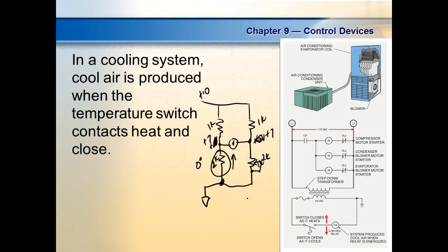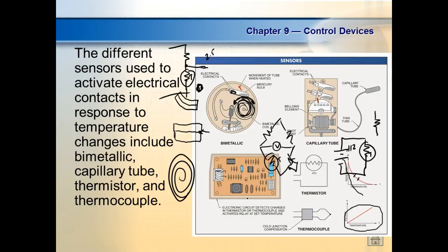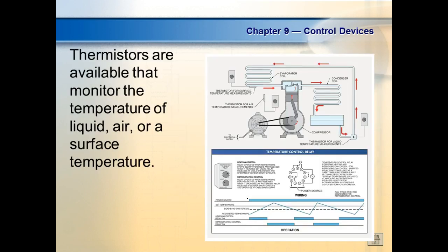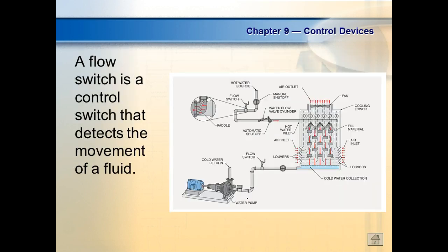I mean, flow switches. We don't have any flow switches. Everybody understand flow switches? Flow switches are usually just vanes we put down inside the flow. It's just like when you're kids and you're driving along, everybody's done this, roll the windows down to do what? Put your arm out. That's basically what a flow switch does.